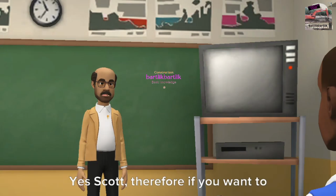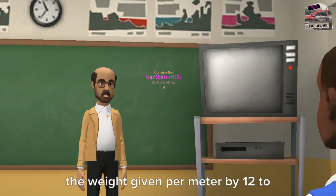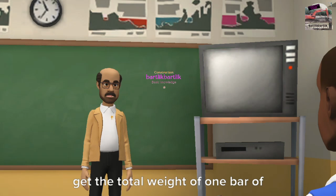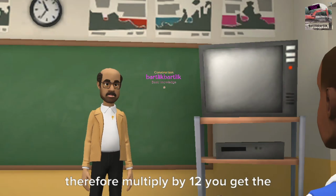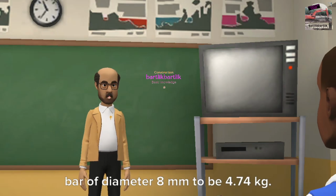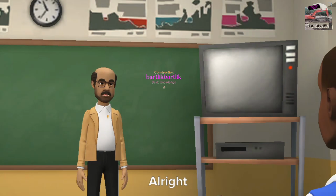Yes, Scott. Therefore, if you want to get the total weight of one entire bar of 12 meters, you just multiply the weight given per meter by 12 to get the total weight of one bar of a given diameter. Example, the weight of 8 mm diameter per meter is 0.395 kilograms. Therefore, multiply by 12, you get the total weight of entire 12 meters long bar of diameter 8 mm to be 4.74 kilograms. Thank you, Mr. Bardlick. Well understood, sir.